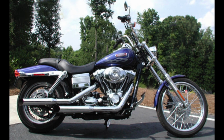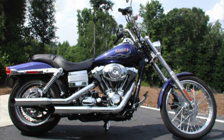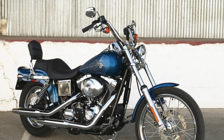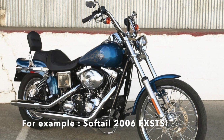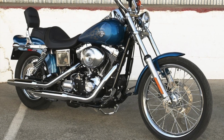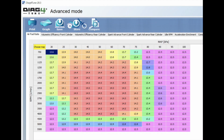Some motorcycle models are equipped with an injection control unit but not oxygen sensors. For these models, the AFR value of 14.6 is replaced by 14.5. This setting essentially still maintains the stoichiometric ratio. The difference in value is minimal. However, having the value set to 14.5 eliminates the oxygen sensor from the equation.